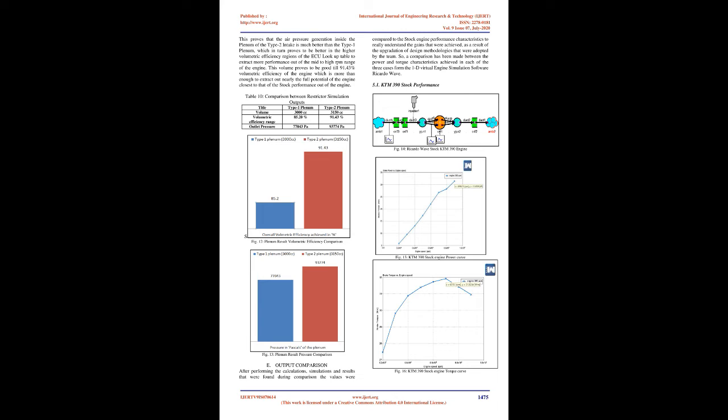According to the availability and part price in the market survey, Tata Nano's throttle body was used, which had a throat diameter of 30 mm, which is the closest to the calculated value. Due to a slight increase of the diameter, the max power curve also shifts to the 10,000 to 11,000 RPM band, which was achieved by changing the RPM limiter in the standalone ECU.